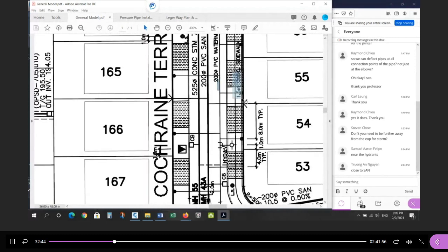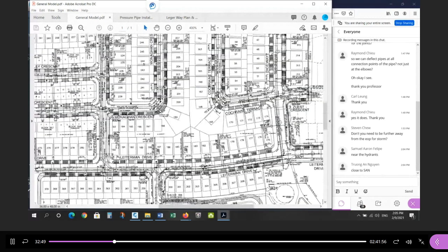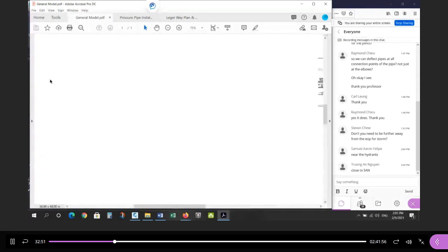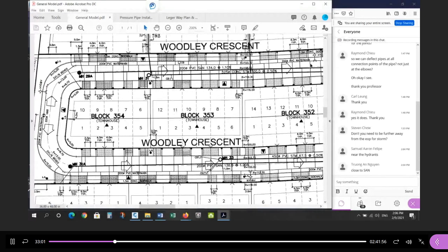Water main, sidewalk on the same side. So if we were to follow that kind of guide, again here, notice the water main is on the north side, it's on the west side, it's on the south side. If chainage is increasing in this direction, it's always on the right side of center, so the sidewalk is on the right side, all the way around.